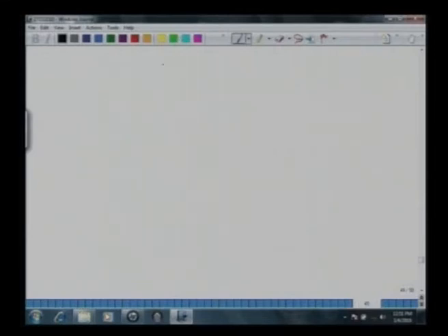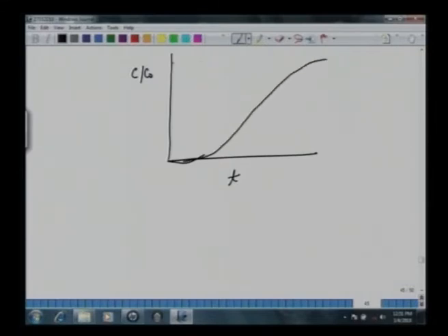So all we do, first we plot this response which we have. This is the time, this is C by C0. If you plot and draw a very nice smooth curve, it's like this. So till t equal to 165 minutes as per the data, there is no response, and at 166.7 one gets a concentration, let's say 0.02 or whatever we have, 0.018.